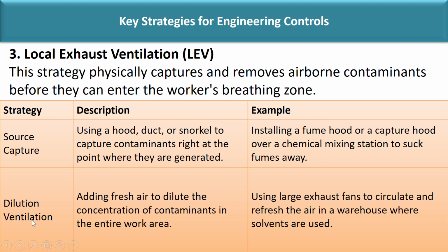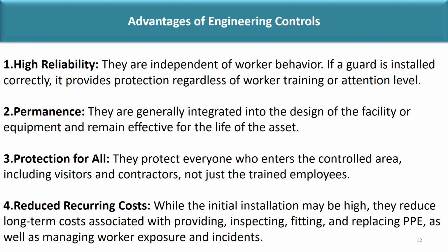Dilution ventilation: adding fresh air to dilute the concentration of contaminants in the entire work area, using large exhaust fans to circulate and refresh the air in a warehouse where solvents are used. Now, advantages of engineering control. What are the advantages we have from the engineering control?